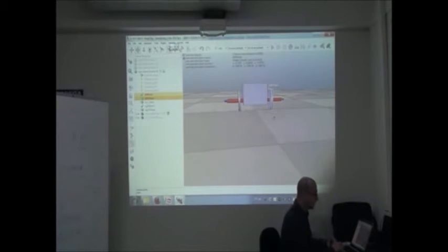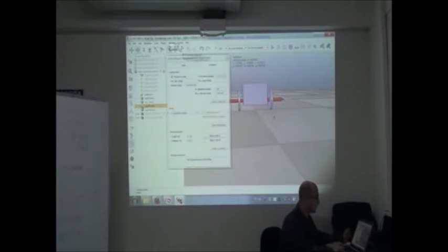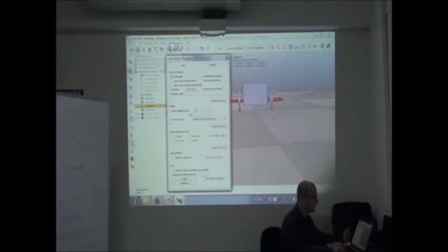Okay? Now this is pretty ugly, I guess, to have those motors shown like that, I mean those joints. I would like them to disappear. Don't you agree? It would be nice. So we want to put them on another layer of visibility. That's the real term. So you click on the right motor, and in the common folder, you have visibility layer, and you can see that it is assigned to this layer. This object is visible in this layer. I can make it visible also here, here, here, in whichever layer you want, but let's do it like this.